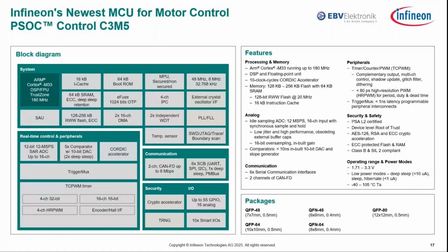I will talk in detail about the 12-bit SAR ADC shortly. Another important block in the analog architecture is the internal comparators, which can be easily used to evaluate the feedback signals needed for motor control. Additionally, in scenarios designed to protect the system, such as overcurrent protection, the necessary reference signals for these comparators can be easily generated using the internal DAC peripherals, digital analog converter peripherals.